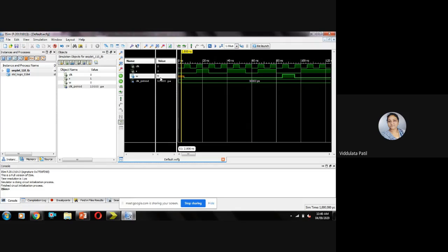But in VHDL, other than these two logic levels, there are certain other logic levels, and one of them is U. U means uninitialized, or we can say an unknown value for the output. So we cannot predict what will be the value of this output signal. Here you will find that it is in orange color. If you zoom in, you can see it is orange, and it is not at an actual logic level 0, nor at high logic level. It is somewhere in between.